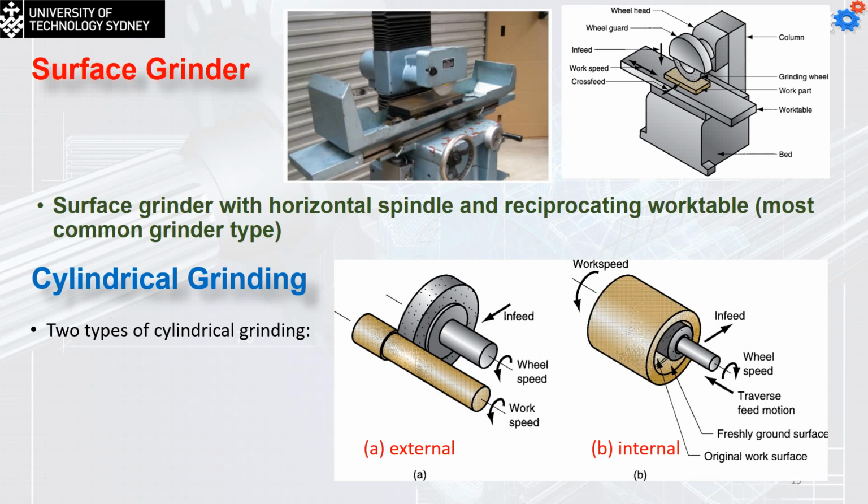Then you will consider what the original cylinder volume was, and that's very simple. Because the maximum diameter you are going to have for the shaft is the diameter of the gear. You add 2 millimeters from each side, and to the height add 2 millimeters from each side, and you will have a cylindrical shape with known diameter for the base and known height. You will find the volume. Now we have two volumes, subtract, and you will find the volume of the removed material.